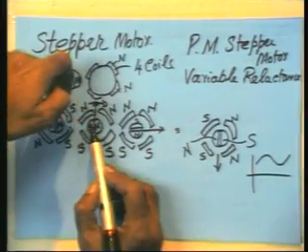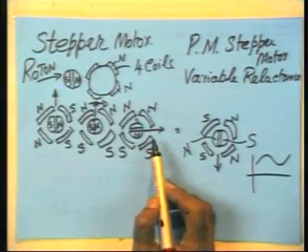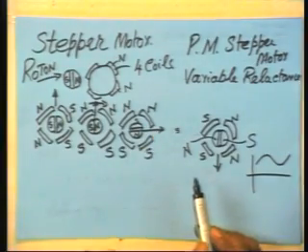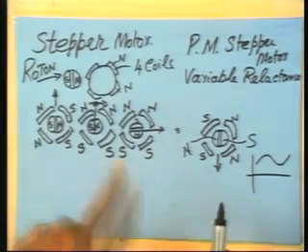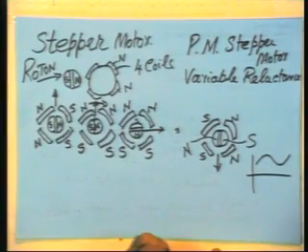There is a huge push here. Towards the end also, there is enough force available, but in the middle, that is the lowest position where, see, if this is a 90 degree one, the one I have shown, in the middle you get the lowest torque. That is the one that governs how much torque the motor can deliver. That is known as the running torque.